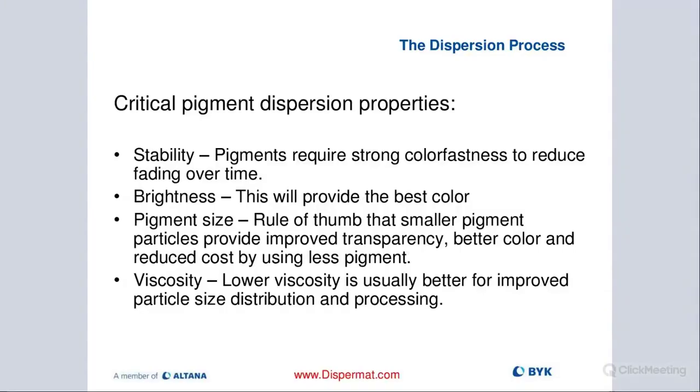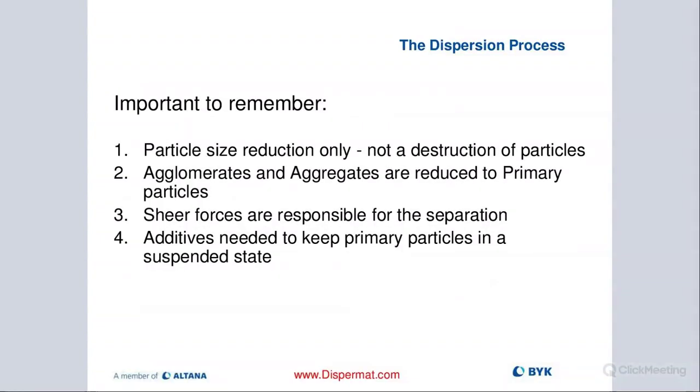And that's also really important. And then another aspect is viscosity. We want to look at that we are in the optimum viscosity window. And that means we don't want to be too thick like a paste because it's very difficult to mill the material. And if we are too thin, then it's very difficult to put in a lot of energy. So we want to be in a good viscosity range, ideally 2,000 to 5,000 centipoise is optimum. That will also allow us to get a good looking donut when we are pre-dispersing. And then obviously when we are milling, we're able to put in the right amount of energy to break open these Van der Waals forces.